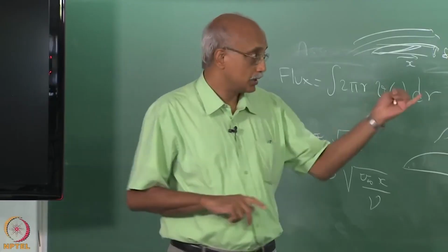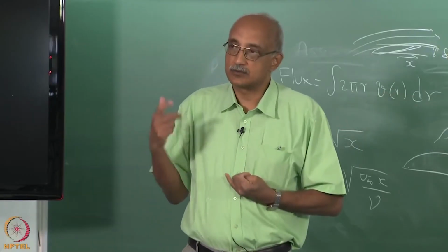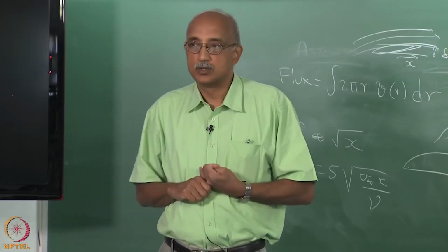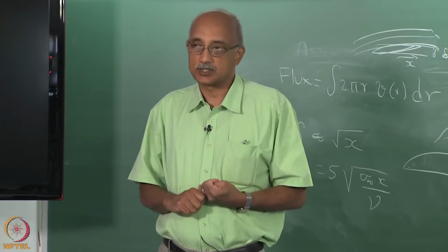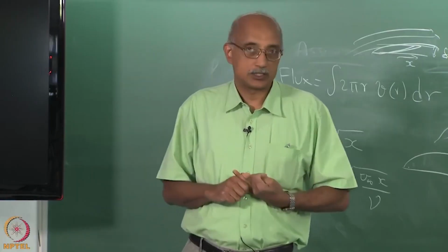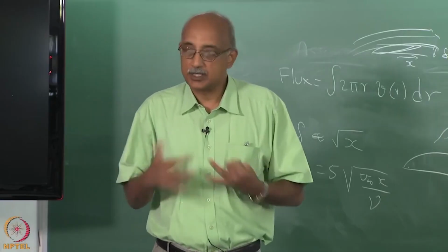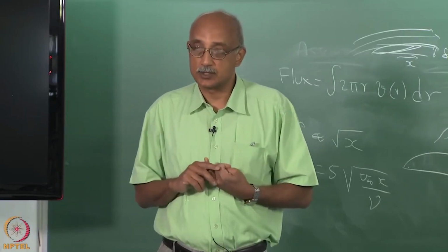It helps ensure that the transition from plug flow to uniform flow or parabolic flow will happen upstream of the substrate. It helps us ensure that there is no turbulence and all the non-uniformities and inconsistencies associated with turbulence.